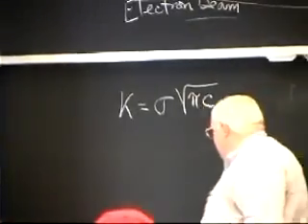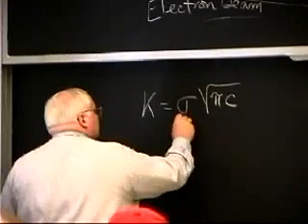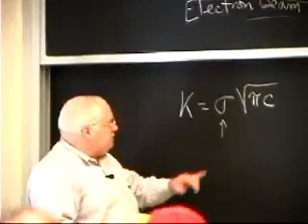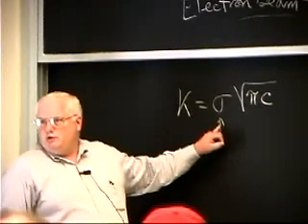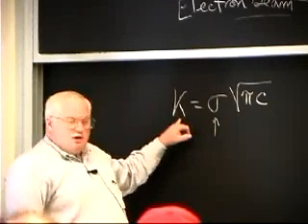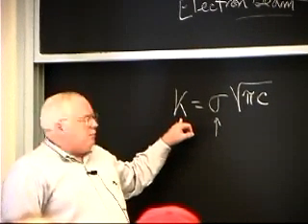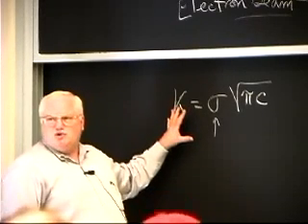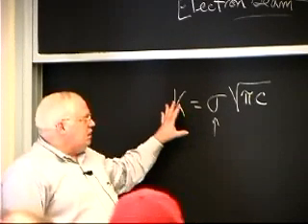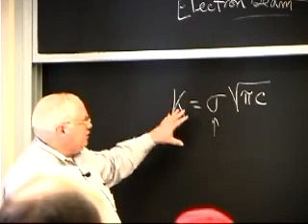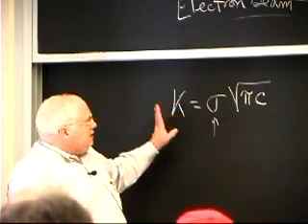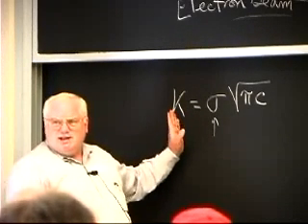In the old days, going up to World War II, 1950, we thought the strength of the structure was related to the stress capability of the material. After we ran into the fracture toughness problem on Liberty ships, we realized the stress intensity. I mean, this was all worked out in 1925, but it didn't really hit home until after World War II, around the 1950s, that we really are interested in the stress intensity, not the stress.